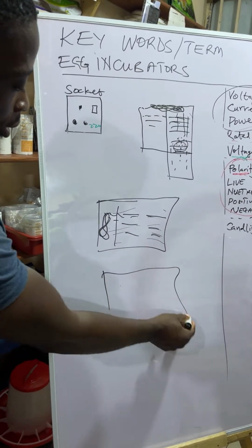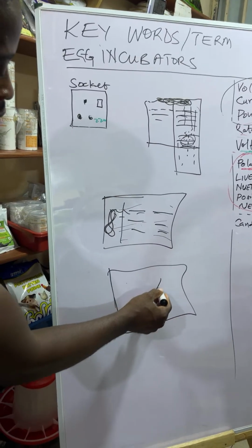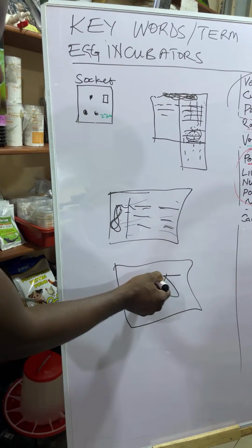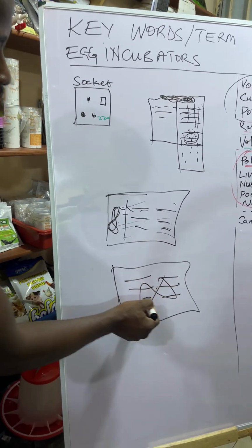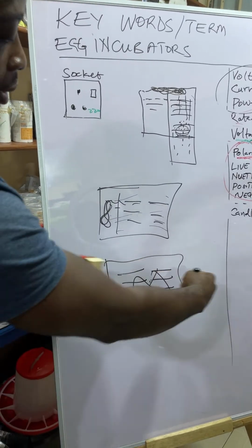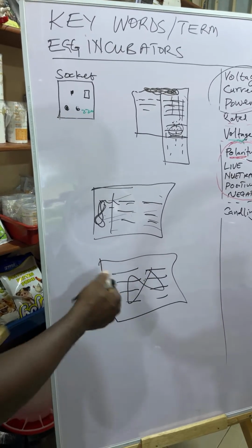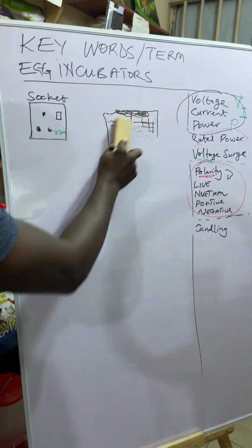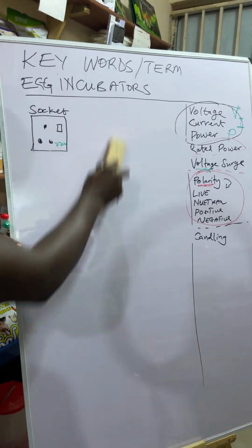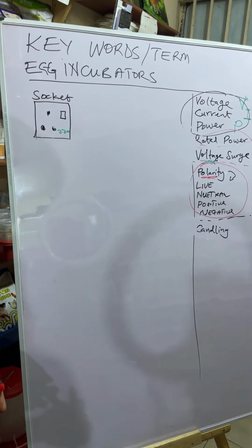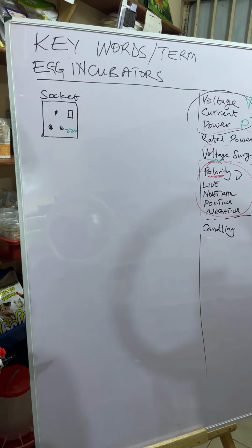Some also put the fan at the back before the trays come. So the fan is behind this and the door is like this. You look at a number of things before you position your fan. The humidity pipe and mist maker would depend on your environment.